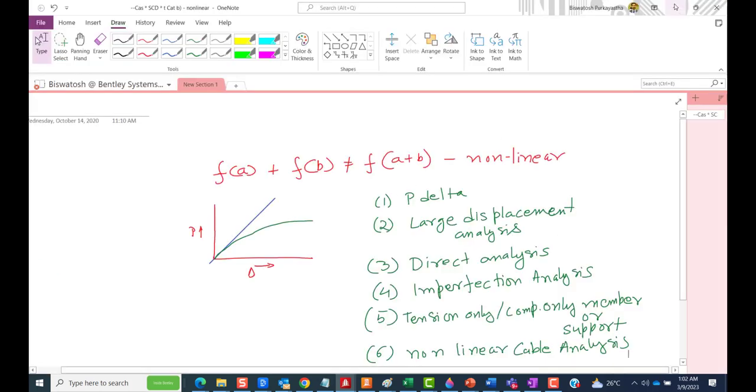Now, before I go ahead discussing the structure, let me first tell you that whenever you are doing this analysis in STAAD, there are a few primary load cases like this and this, and eventually you are doing some combinations to find the envelope of all those loading actions, finding which is the most critical one and designing against that. Now, whenever you are going to find the combined response, you must be very careful about taking the right method of combining those primary load cases.